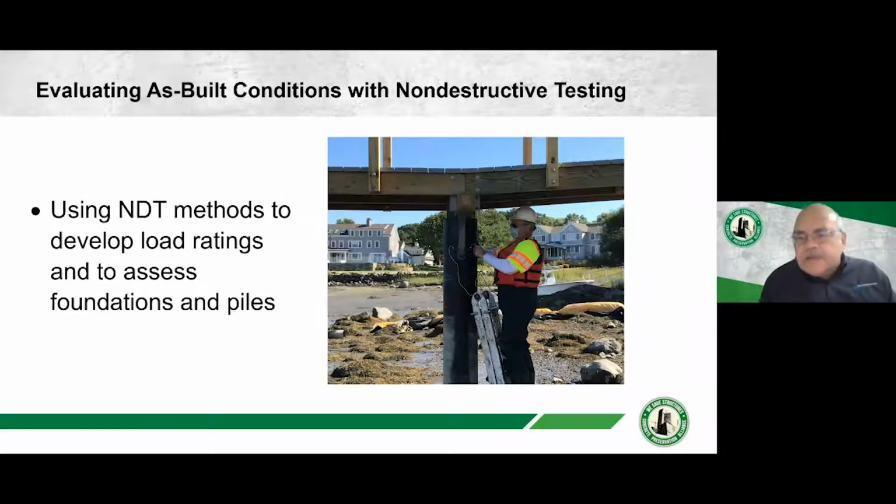Great. Yes, it is myself, Chris. We're testing some piles. We've got our sonic, ultrasonic testing, and we're testing for the embedment length of piles. This happened to be a new pile that was driven, and the owner wanted to verify the embedment depth.